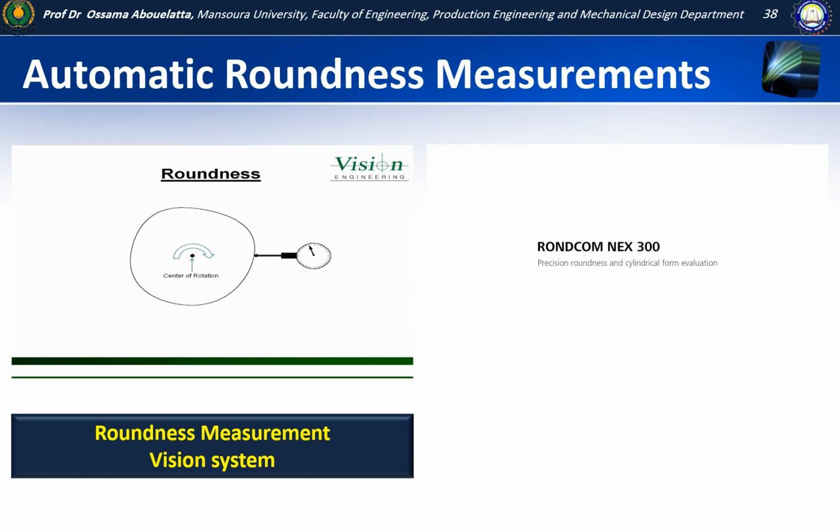As we rotate the part, the total indicator reading is our roundness value. And providing that our total indicator reading does not go outside of our tolerance zone of 0.005, then the part can be considered as in tolerance. If it goes outside of this tolerance zone, then the part is out of round. Now let's take a look at how we'd inspect roundness in our readout.